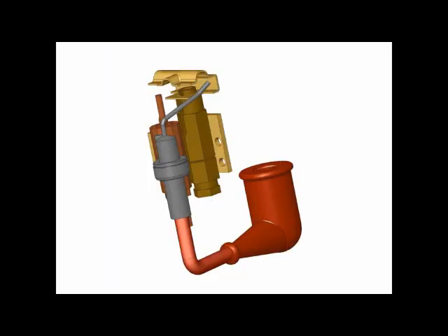The spark and gas arrive at the pilot, igniting a pilot flame, which contacts the flame sensor, generating microamps that are sent to the module on the sense wire. When the module senses the pilot, the spark stops and the module outputs 24 volts AC from MV3.